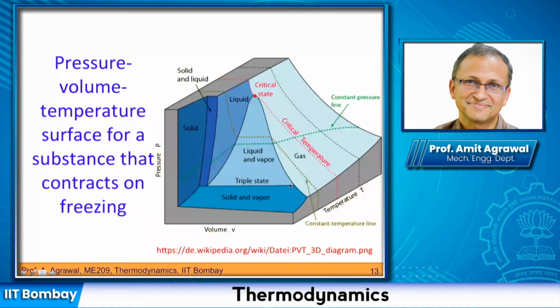To summarize, we saw two points, C and T. C still is a point, but T is not really a point. It's actually a line. We were getting it as a point because we were taking a projection of this line, and our line was just orthogonal to our view. So that's one thing that you can see from this solid.